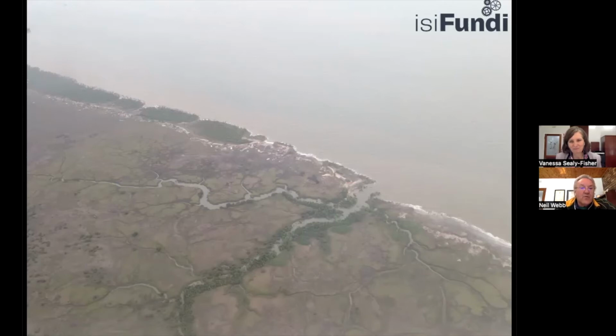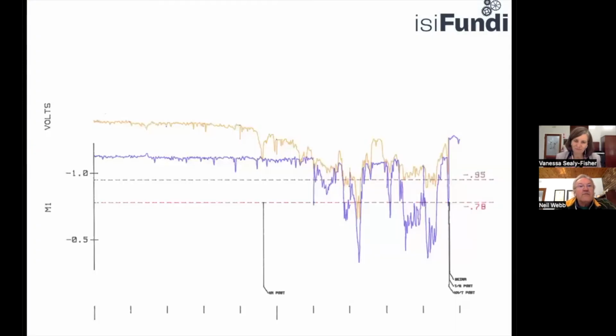It was a highly corrosive area. But what was the interesting point about this is that one of the few rectifiers that had been maintained on this line was located in this first section of the pipeline. And when we did the close interval survey, which one would have done in an indirect assessment phase of the project, we discovered that there was only about 1 kilometer of the pipeline where the wrapping was in very poor condition. And for the rest, potential was pretty good.